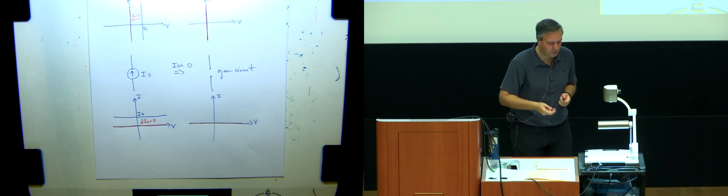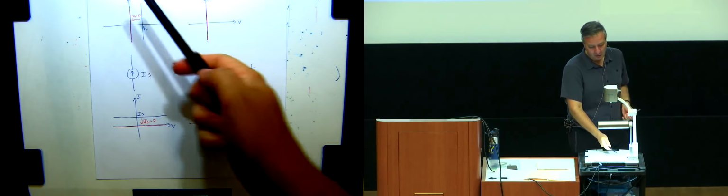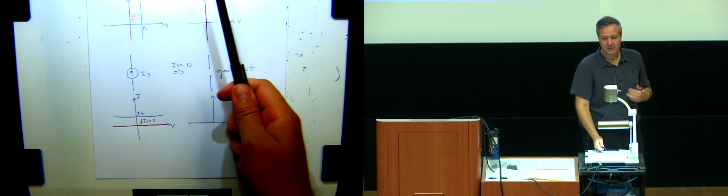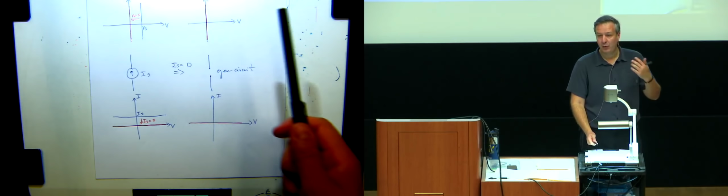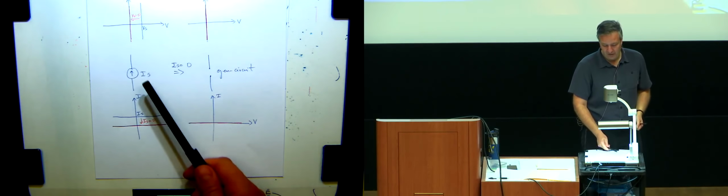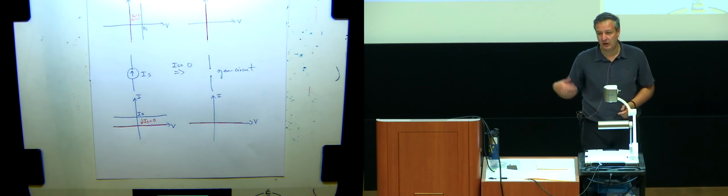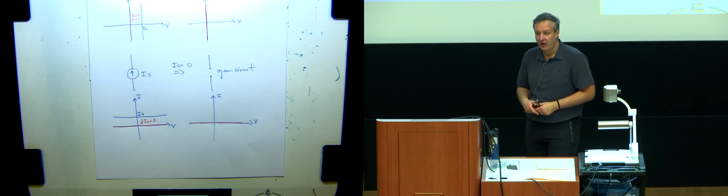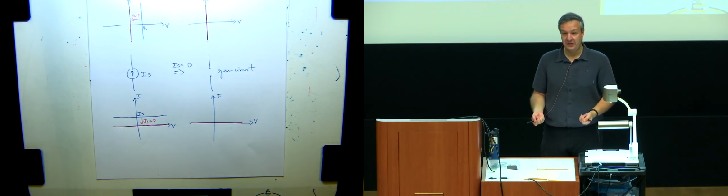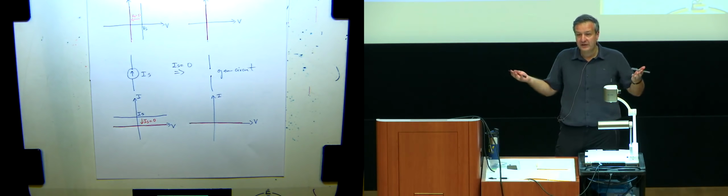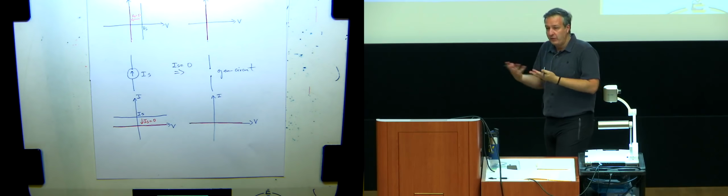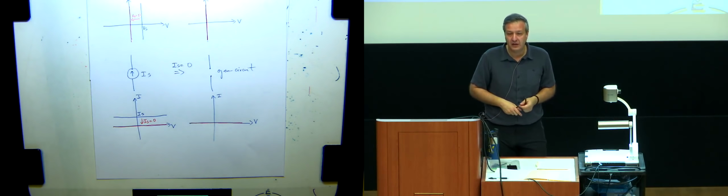Yeah, so the comment was, all the voltage sources that I'm looking to null, I'll replace with a wire. All the current sources I'm looking to null, I'll replace with an open circuit. A wire was already a very simple thing for us. There's a wire between the two nodes, we know it's the same potential. If there's an open, we know there's zero current. We don't even need to calculate it.